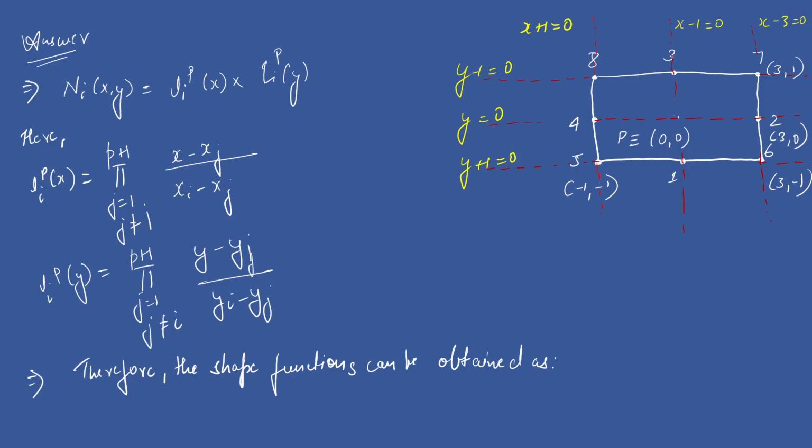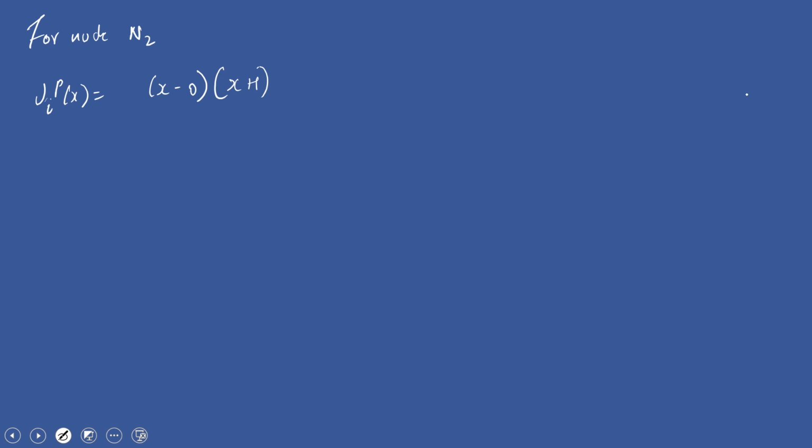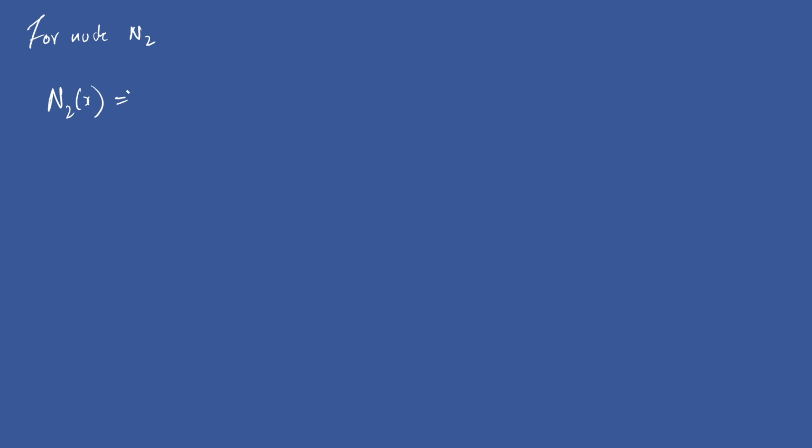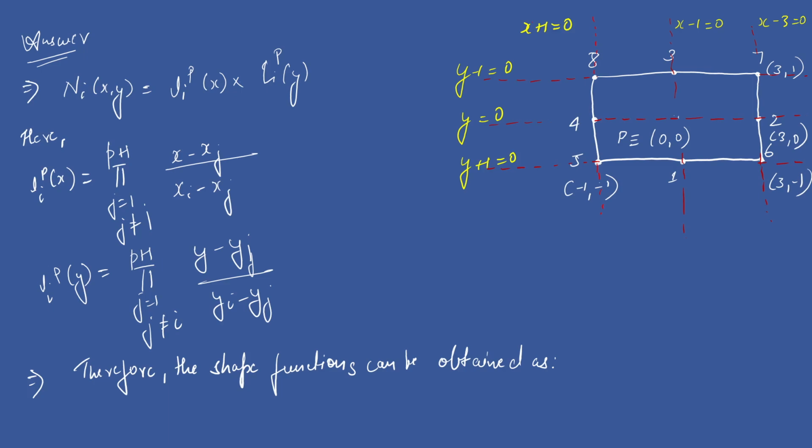Yeah, now it's fine. So for this particular second node you want to evaluate, so if you see the Lagrangian interpolation function, which is directly we can calculate what is the shape function available with you. So for the n2x, the shape function which is there with you, it is the product of LITX and LITY.